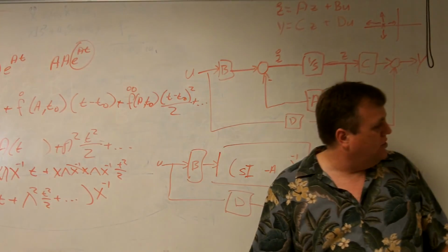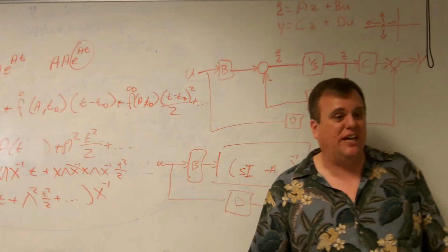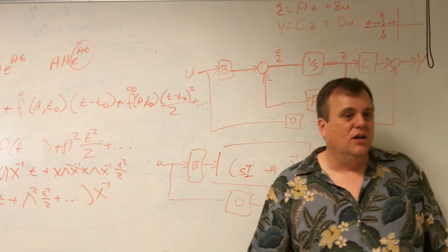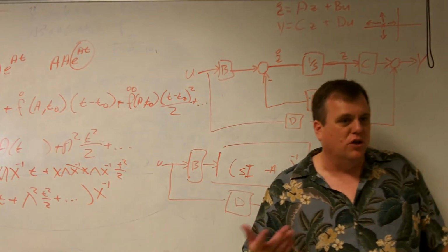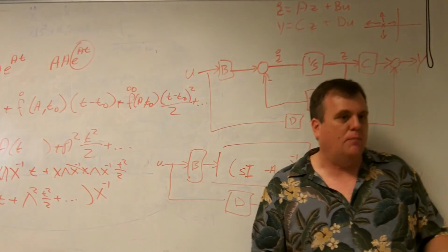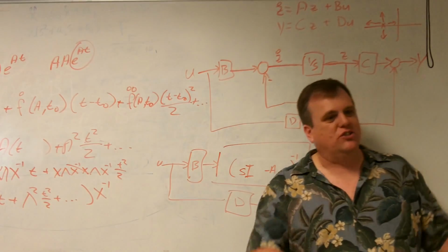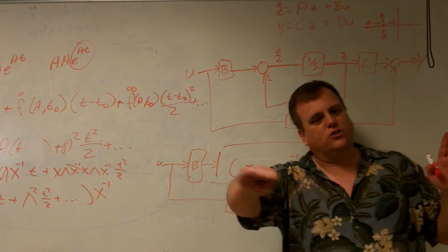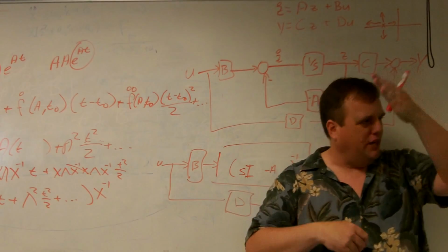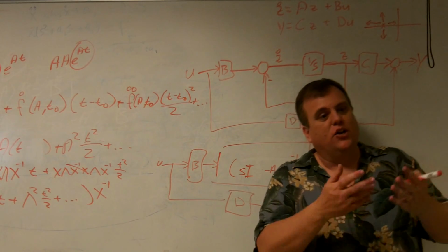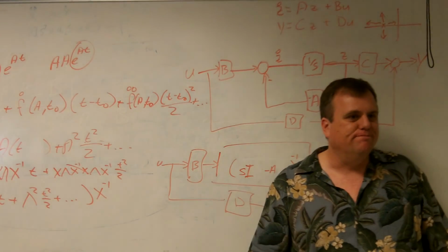Actually, believe it or not, the matrix ways of solving these in general for nonlinear stuff came out in the 1800s. It just wasn't applied. A Russian mathematician named Lyapunov came up with one of the most general things, what are called Lyapunov functions, and it's basically an energy thing. His basic theory says, if you watch the trajectories of your system, and you give it some input and look at the outputs, if along every possible output line whatever energy function you picked is always decreasing, it's stable.